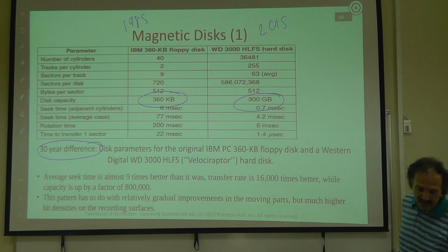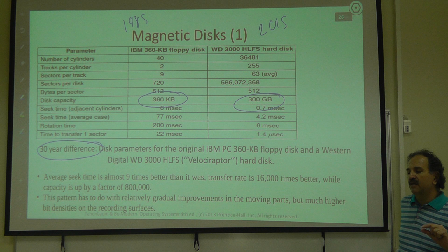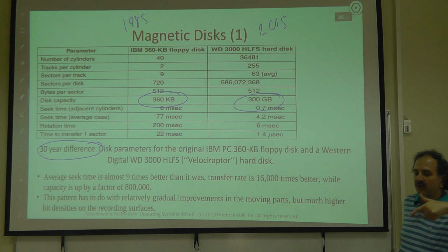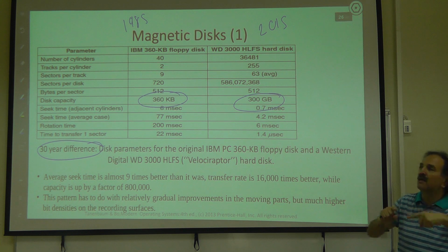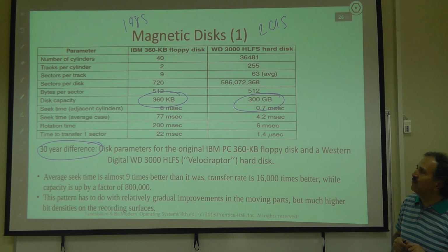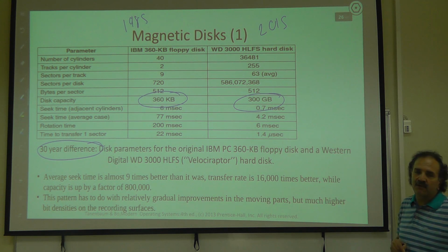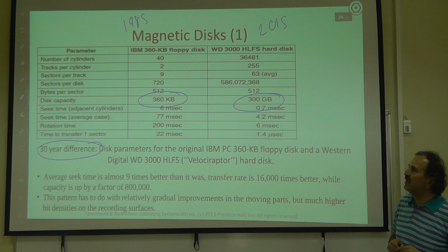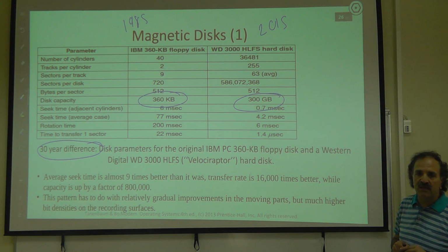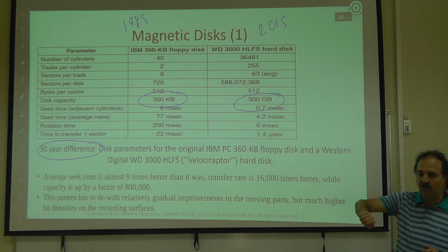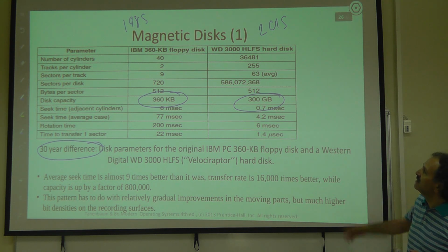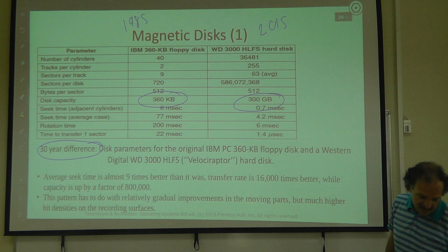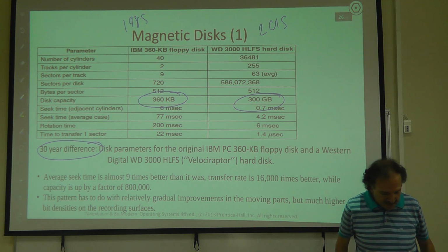This one has only a single disk, a floppy disk. You have only one head for the upper side of the disk, and one head for the lower side of the disk. And even in those days, for some cheap drives, they had only one head. In that case, you had 180 kilobytes of data. You needed to remove your disk, reverse it, and put it in again. So that was the case. This guy has this many, 255.